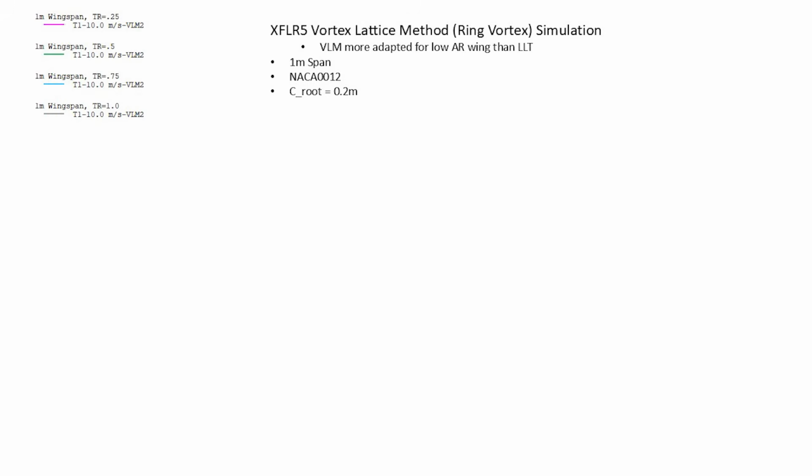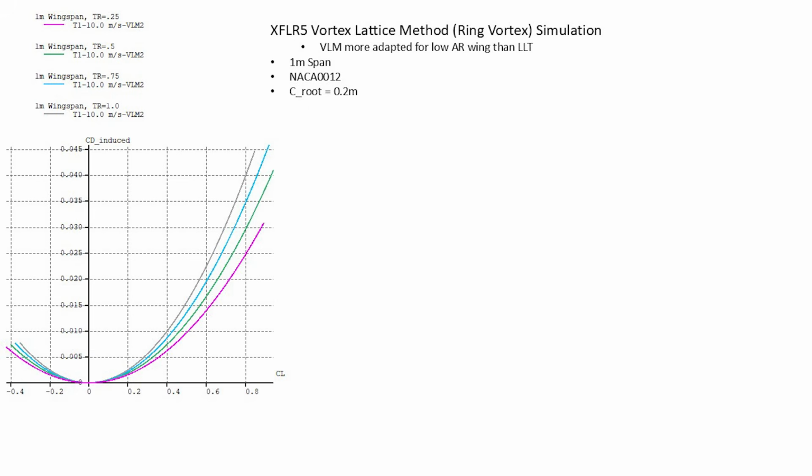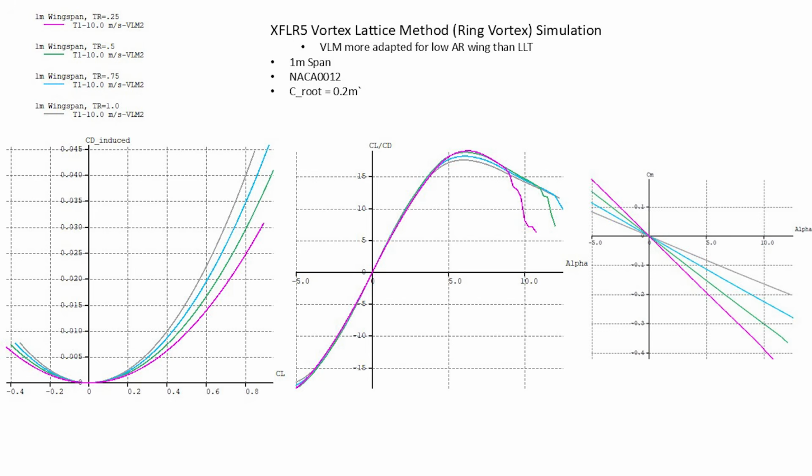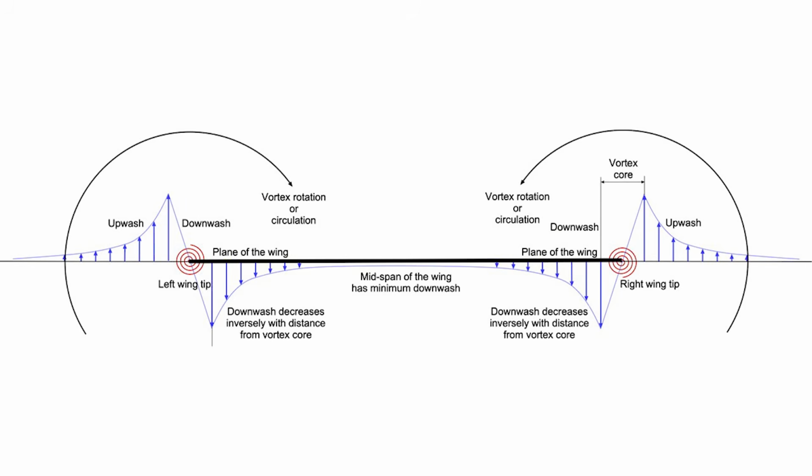The magnitude of this vortex is directly proportional to the pressure difference between the high pressure and low pressure regions on the wing, so by tapering this wing, the lift distribution becomes more gradual towards the wingtips. Aerodynamically, wingtips are the least efficient region of the wing, generating the most drag for the least amount of lift, especially without winglets or end plates present.